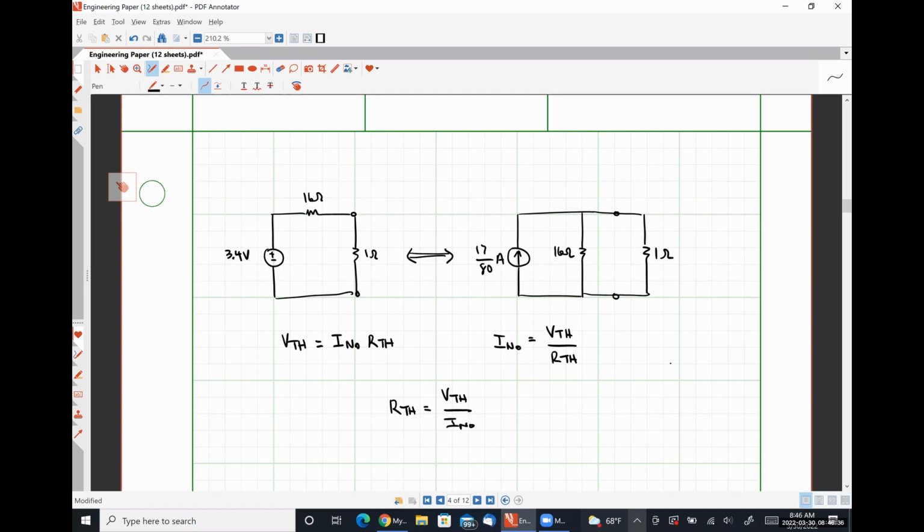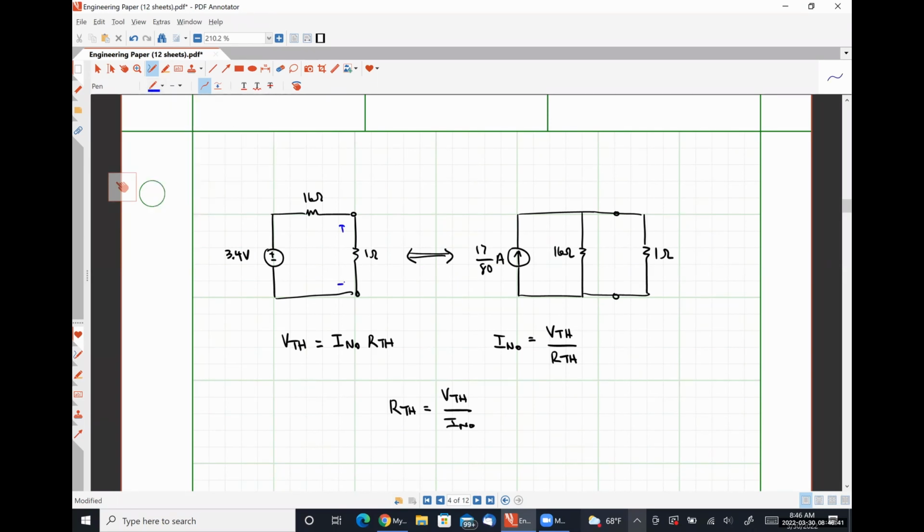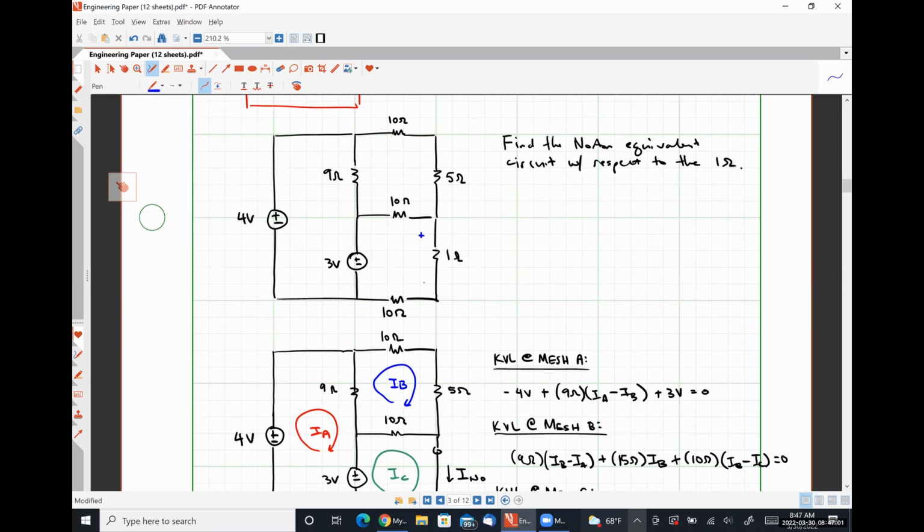And the voltage drop, so let's just be explicit here. Let's call this VL, this IL, this VL, this IL. Obviously, VL has to be the same, IL has to be the same, and if we were to look at our original circuit, the values of VL and IL that we calculate using our Thevenin equivalent are the exact same as that we would observe in the full circuit. They have to be, or they're not electrically equivalent.